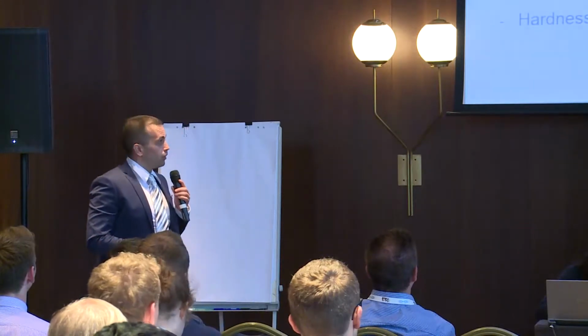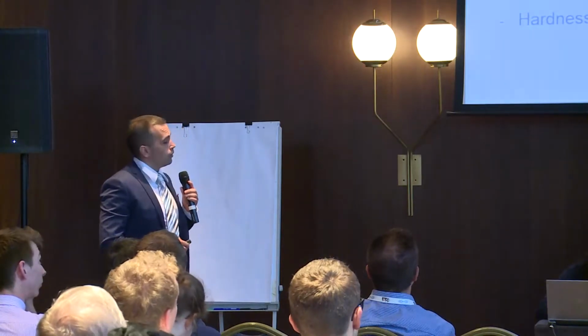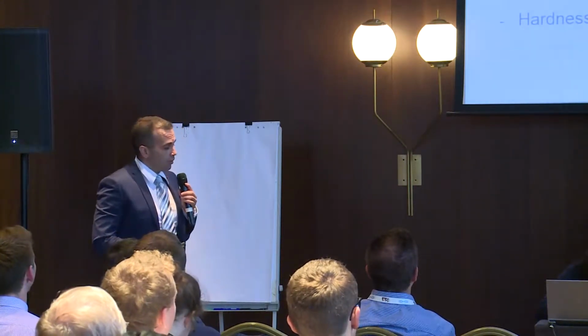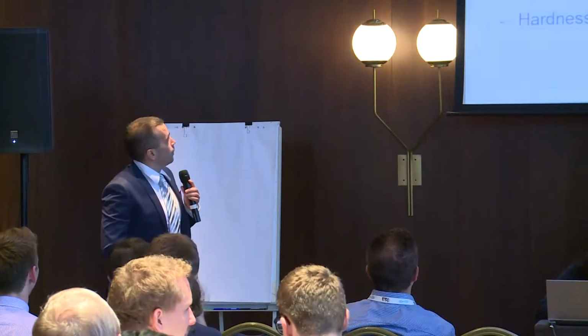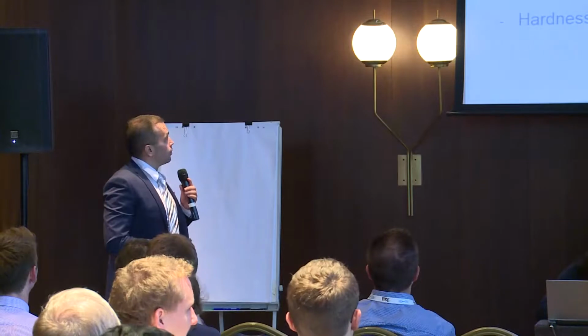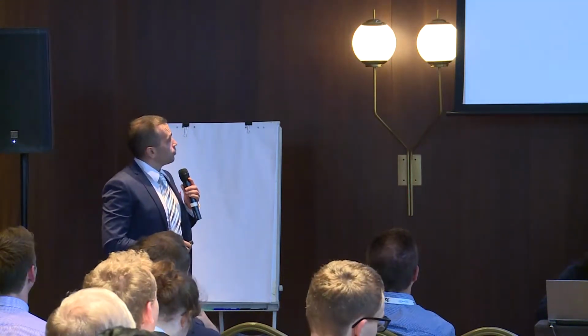Introduction to weldability. In this research, we weld Protac 500 armor steel made in Croatia, developed for construction of military vehicles. The microstructure consists of tempered martensite. Hardness level is 509 Vickers.